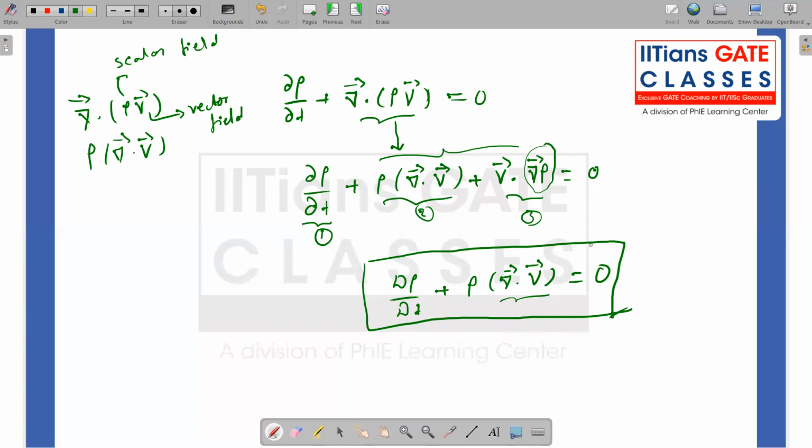But it is not necessary that if the divergence of the vector is zero, my flow field is always incompressible. It is not necessarily true, but it is a very important condition when we define potential flows, because potential flow can be defined in pure incompressible and irrotational flows, as well as irrotational compressible flows also. We can use the divergence.